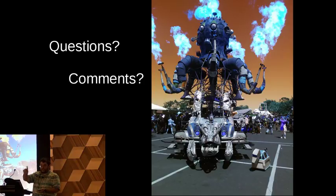Usually on a good machine that does this, it runs the part over a camera to double check the placement and to make sure it picked up the right part, because sometimes they pick up the wrong part, or they drop the part, or things explode. Then it moves it over to where, on your original layout file, there's an entire orientation and absolute positioning file that you generate from that for the manufacturing process. It then places it on little daubs of solder paste. And once everything's on one specific side of the board, they run it through an oven and bake the whole thing in a very specific way, which sets the solder and locks it into place.